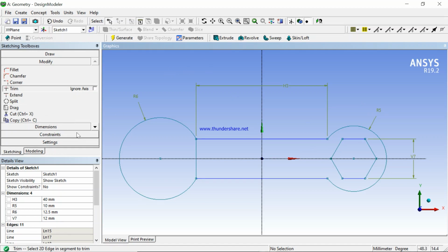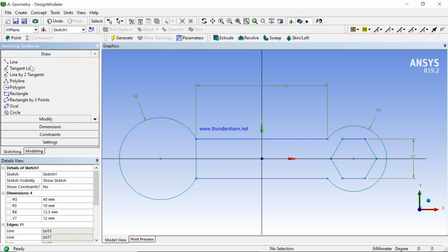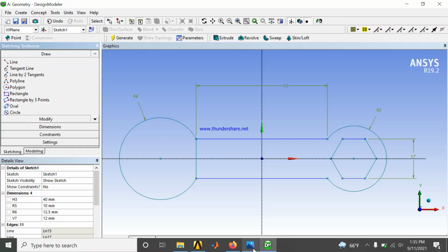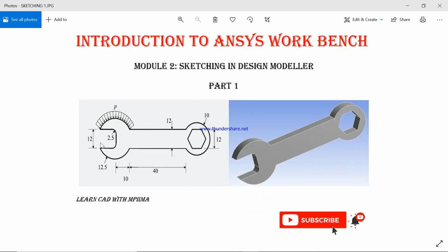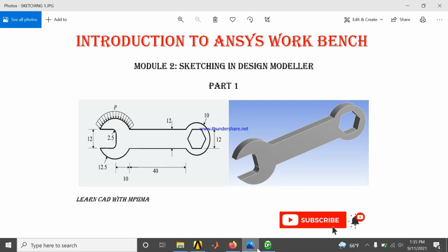On the other side, we have an opening, so we can draw that. It is also centered. I can still use a rectangle. I can use a rectangle with a fillet of 2.5.